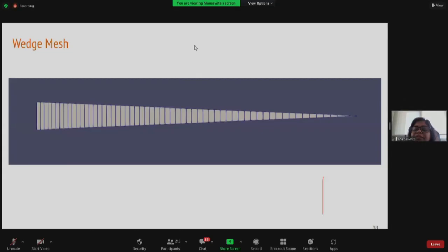Zero velocity, you mean zero velocity gradient or constant pressure? No, at the outlet, sometimes we use zero pressure gradient, and sometimes a constant pressure. Is there any specific criteria? You use zero pressure gradient, dP/dn equal to 0, at the outlet.